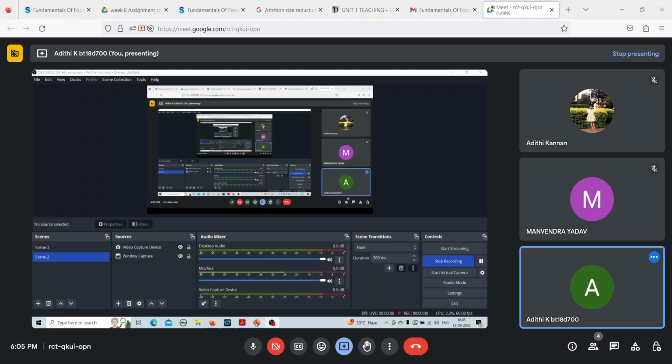So when you have a very slow rotating speed, this is how your balls will fall. It will be sticking to the wall for a time, and since the speed is pretty less, the balls will lose contact with the walls and fall down, hit the food and reduce the size.